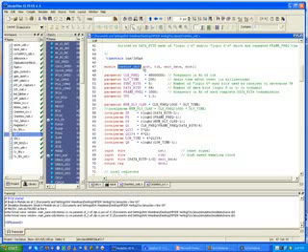There are different ways of writing, but the reason I do this method is I list my signals on the module line here, but I don't actually declare whether they're input or wire yet. The reason is that I want to put my parameters in here because I may do some calculations, like these local params, based on these parameters. So they need to be after parameter, and then I may want to change widths of things based on those parameters. That's why I want them all before my actual input declaration here. So this is a general format that I use all the time.